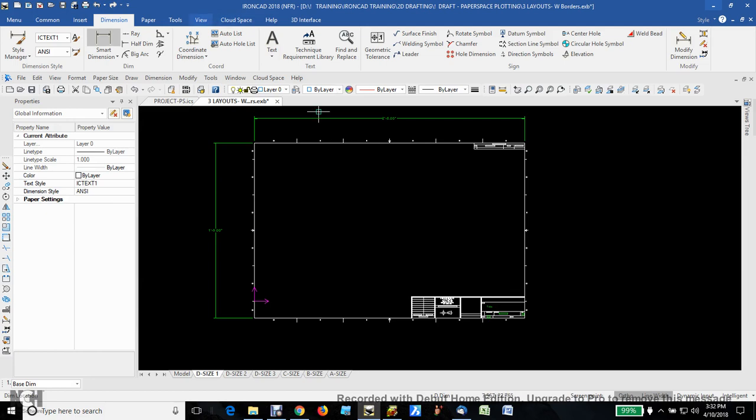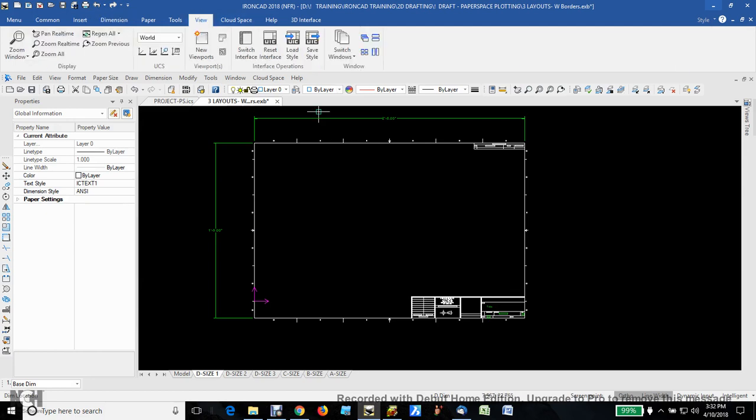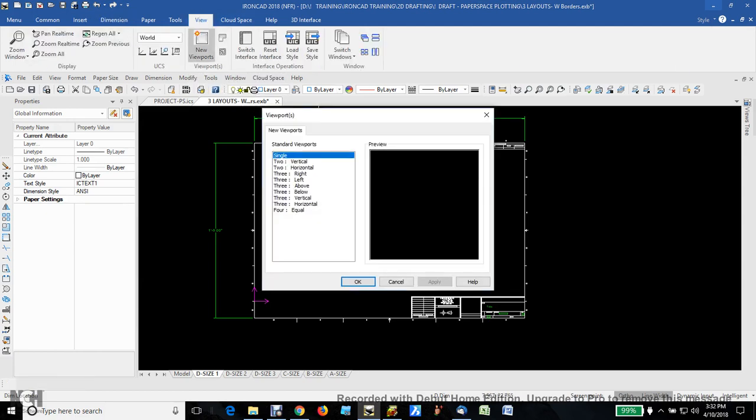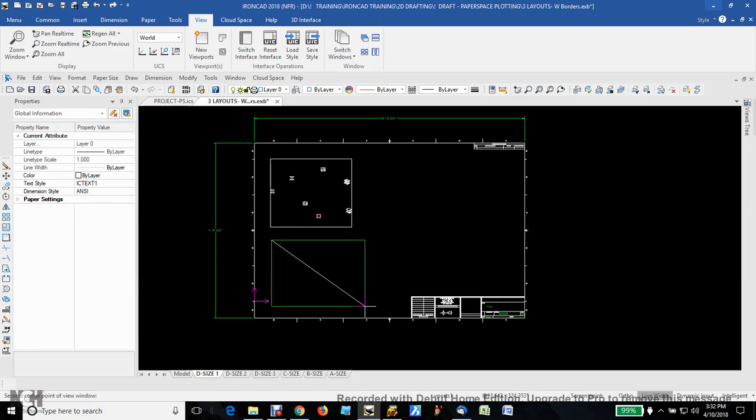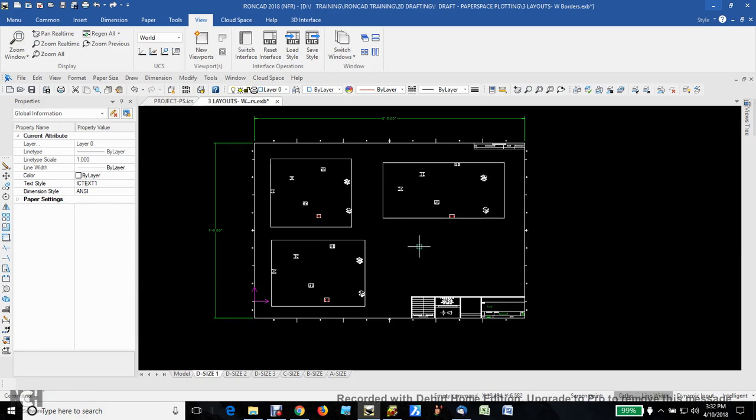So here I come up under View, pick Viewports, select, I want a single. You can have as many as you want here, 4 views. I want to do a single at a time, so I select, create a window. So there are my views, and this is a window, but it looks back into your model space. Hit my space bar again to get back into the last command. Put another view down, space bar. Put another view down, space bar, and put one more view down.